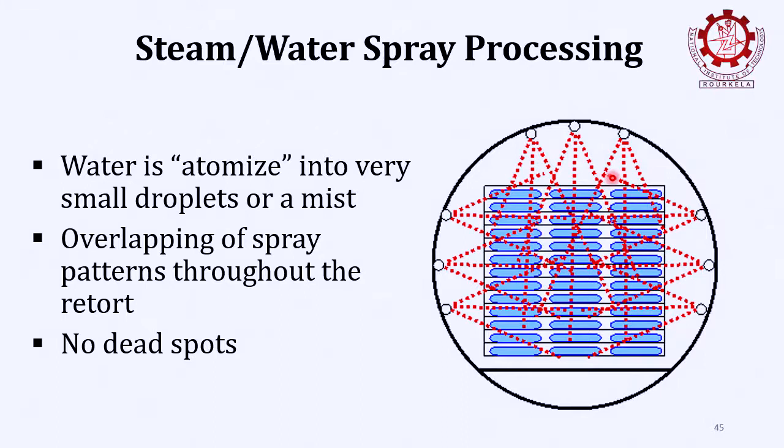I can make a smaller one having better uniformity, but then the throughput for the company would be very, very low, and the whole process becomes very expensive. So they try to have fans inside that recirculate the media very effectively, or try to have multiple nozzles so you can spray and cover as much area as possible, so you create minimal non-uniformity, or you reduce the non-uniformity.